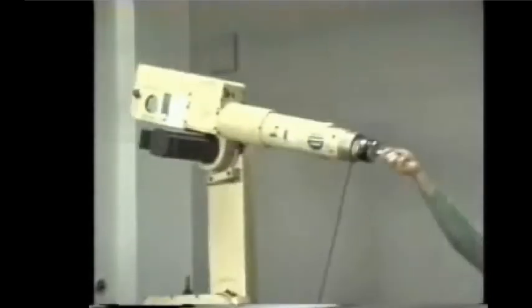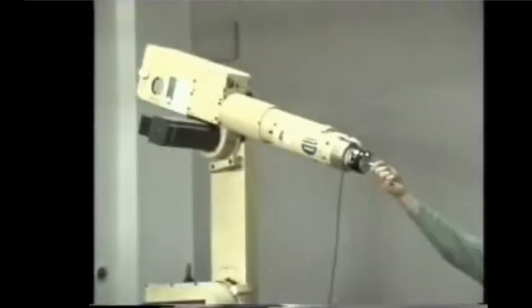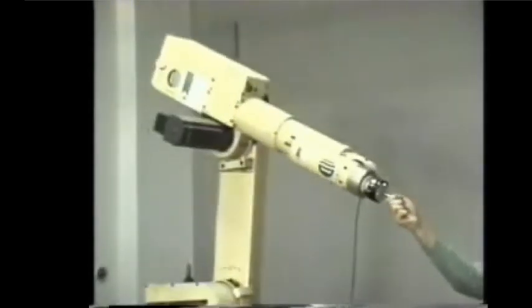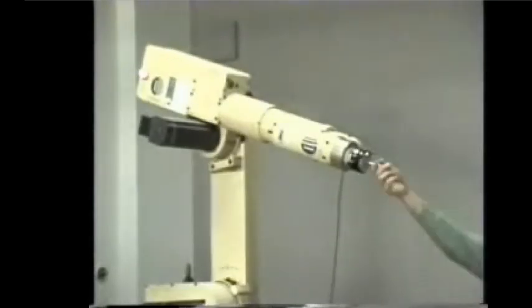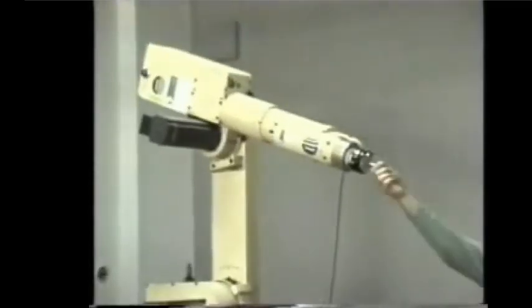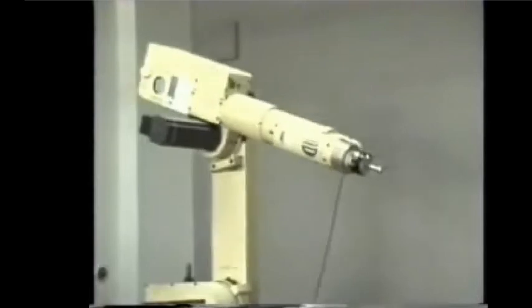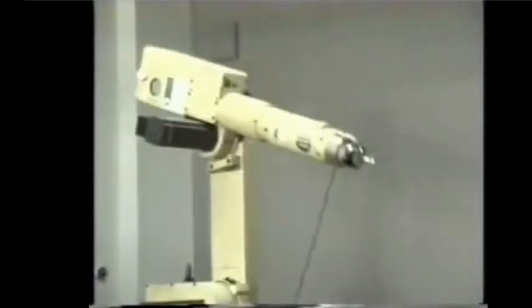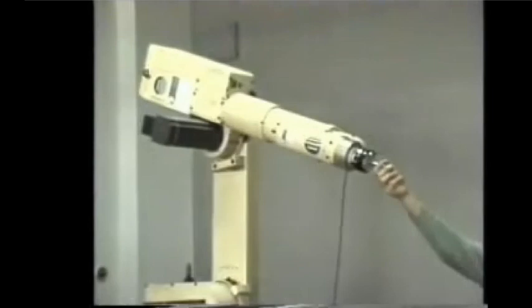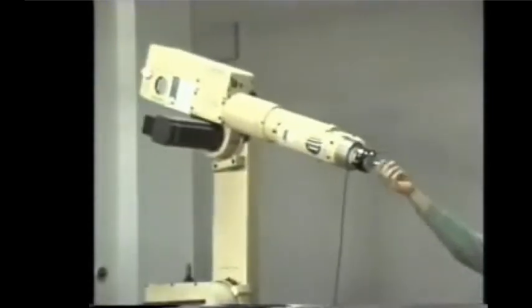Here you see that lower stiffness corresponds to larger motion. And then when you release, the robot will go back to the same position. Now you can also choose a stiffness and the apparent mass, and change the damping. If you use large damping, you have a small overshoot, but if you use low damping, like in this case, you will see oscillation and overshoot with respect to the desired position. So you can see that those parameters play a very nice role.